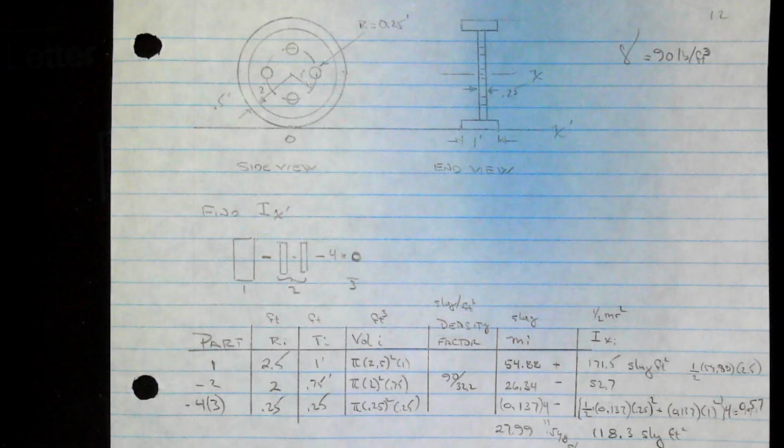Now, relative to Z1, we don't need the total mass. We'll need that in a moment. So we had the first cone, 3/10, mass 1, which is up here. Its radius was 0.8 meters. We'll square it. The second one, the tip which was cut off, 3/10, the mass which is up here, we're subtracting because we cut it away, 0.2 squared. And then the one that was countersunk, 3/10 m3, 0.2 squared as well.